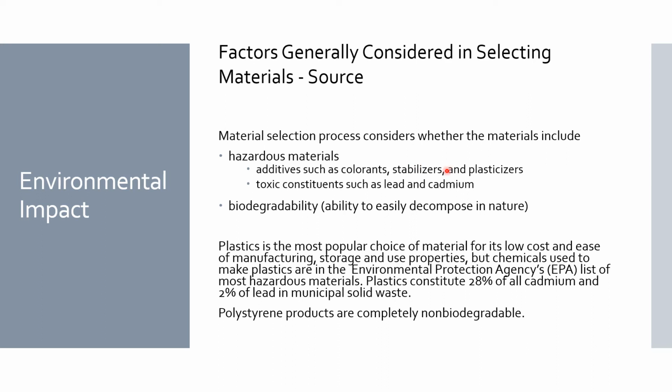Percentages are so important. So think about the additives, like your colorants, your stabilizers, your plasticizers, okay, toxic constituents like lead, which is an important thing, and cadmium, because they cause cancers, things like that. Okay, very environmentally unfriendly metals. Okay, so biodegradability, you have to think about that as well when you choose the materials.